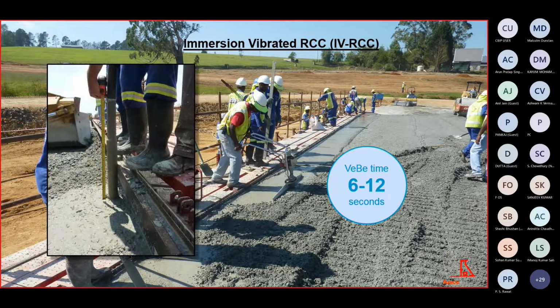Immersion vibration crosses the 300 mm thick layer and penetrates in total around 500 mm down into the concrete, as shown here. In hot condition, when the second lower layer has not initiated set, this leads to a complete interpenetration of both layers and the elimination of the physical joint plane between them, achieving an excellent bonding and impermeability. This has been investigated by testing cores drilled in this and in the area compacted by the rollers. An excellent lift joint behavior has been observed in both cases.